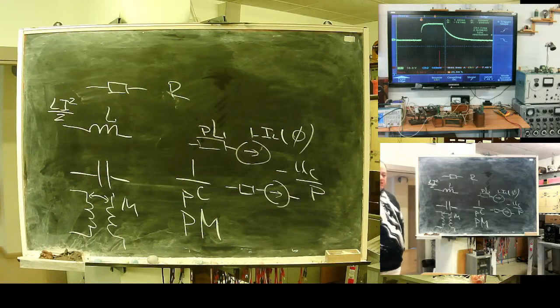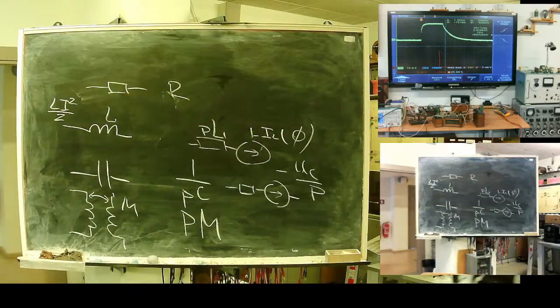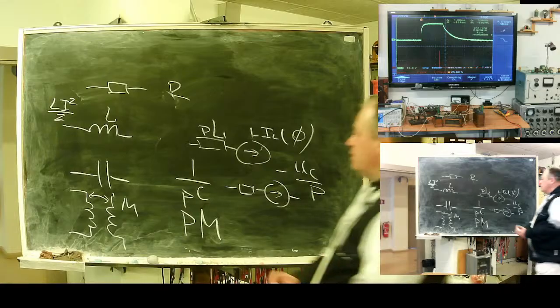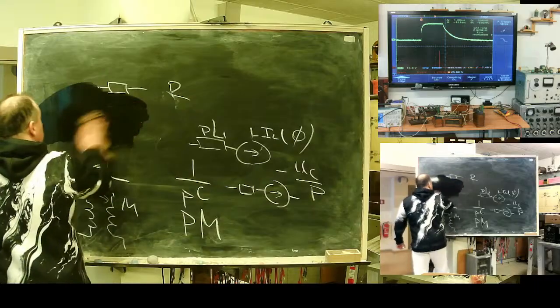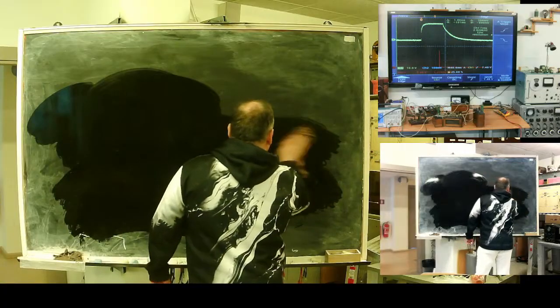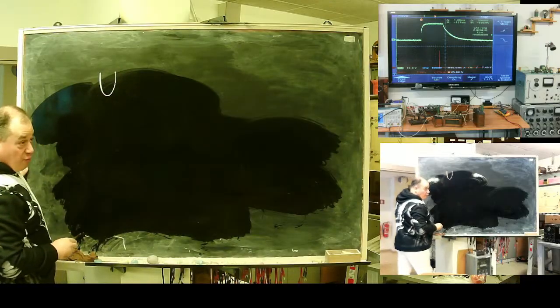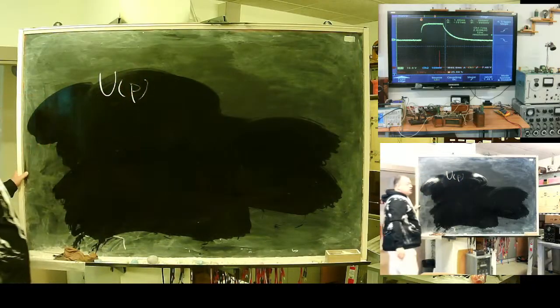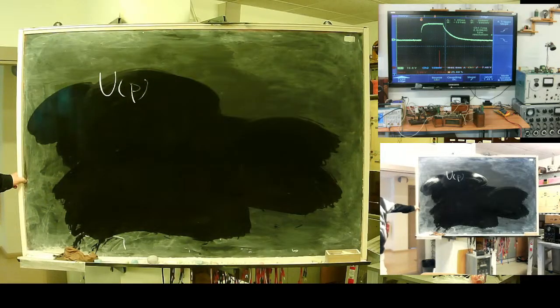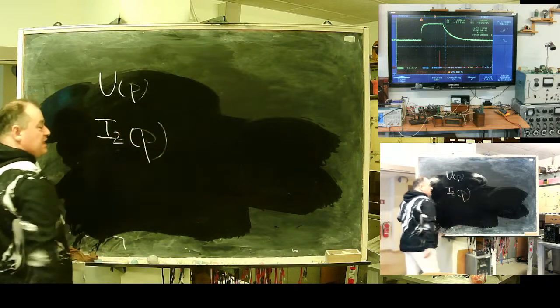Your schematic will be solvable with a simple technique of circuit solution, for example, with the nodal voltage technique. What will you get? Direct solution of the network will yield node voltages as a function of complex frequency, or images of nodal voltage, and branch currents as an image.